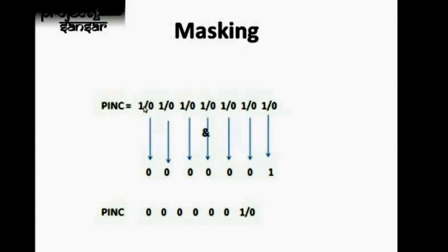So for example, if there is a floating voltage or an unwanted input in the pins, my input reading would not be affected by it, because even if it's 1, I AND it with 0, my output would always be 0. Rest for all. But when you come to pin 0, if it's 1, I AND it with 1, I get an output 1.